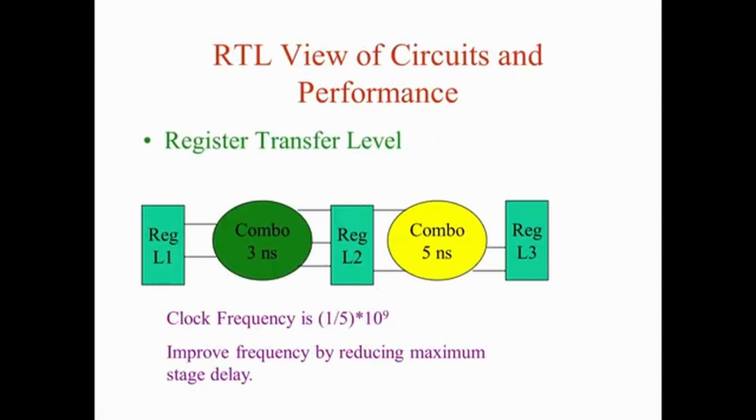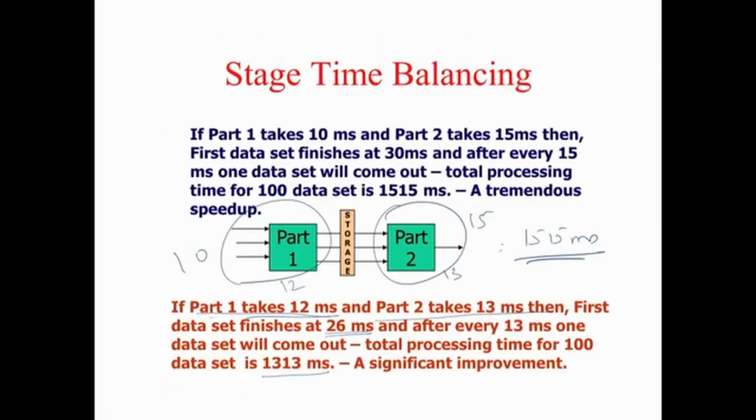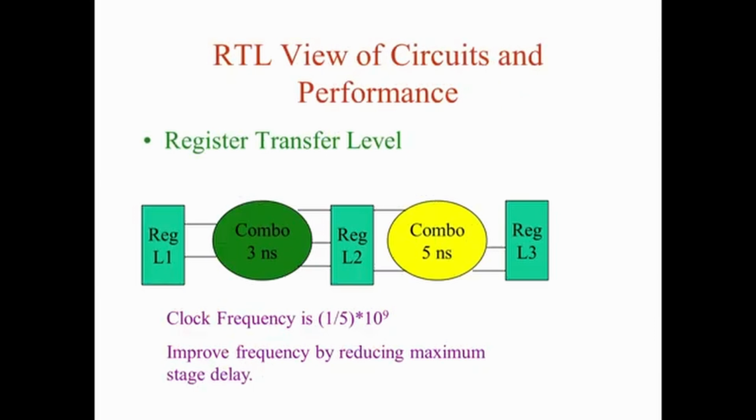Is it okay? Now let us talk about what is register transfer. Already we have seen in a pipeline circuit there is some register feeding a combinational circuit which will again feed a register which will again feed a combinational circuit. So the way we describe the design is how some set of data moves from one register to another. That is why we call this RTL, register transfer level. The entire modeling of this is done through RTL.